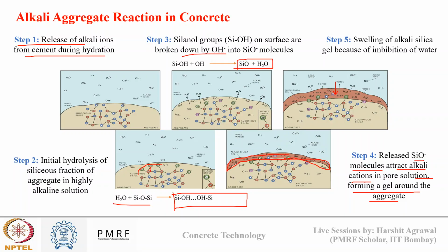So initially there is release of alkali ions. The reactive silica in concrete, in the presence of alkali ions, forms silanol groups, SiOH groups. These SiOH groups further break down in the presence of the alkali environment into SiO negative ions, and these negative ions react with the cations which are present in the pore solution to form a gel around the aggregates which has the ability to absorb water and expand.